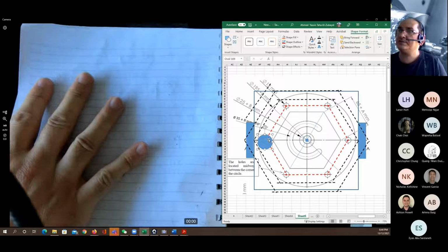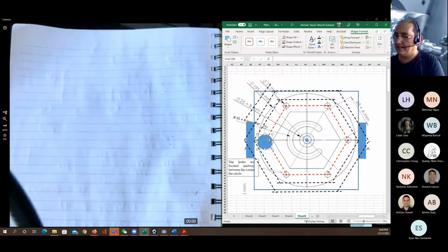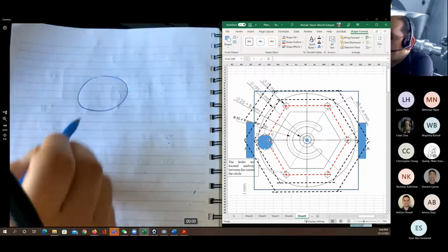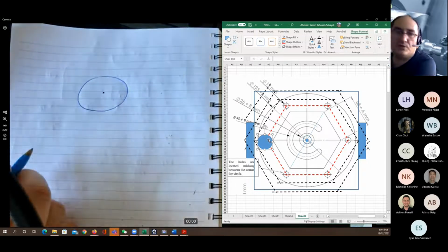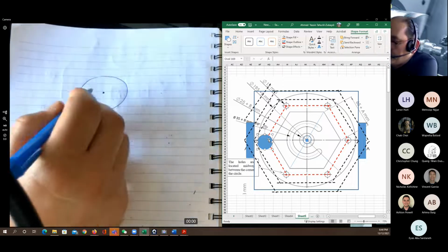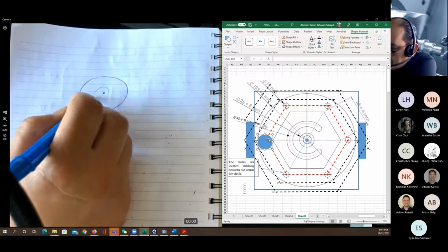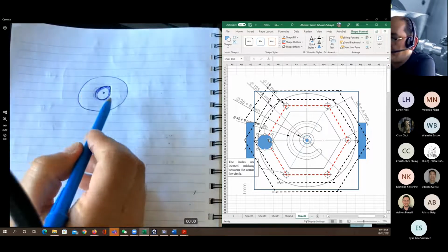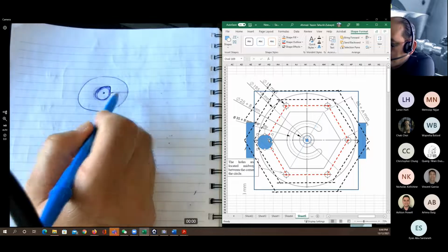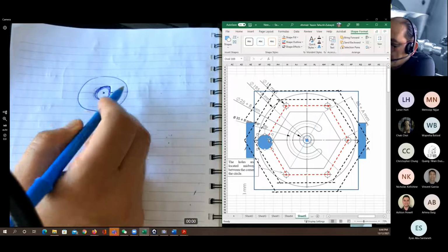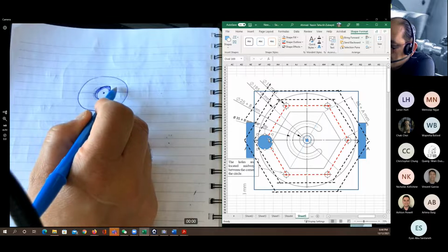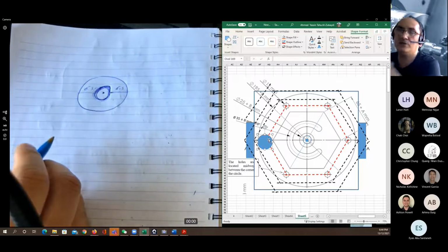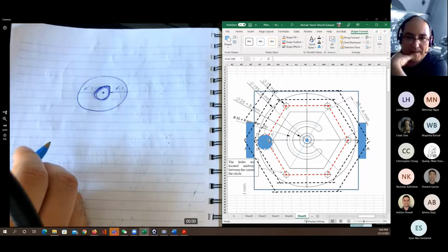Now I will sketch just the circle in the middle individually. The center of the circle is the datum point, which is 0, 0. If I put my cutting tool in the middle, it is 12 millimeter diameter. That means I'm also going to have on the sides, about 6.5 in each direction, that needs to be removed. So how can we solve this problem?